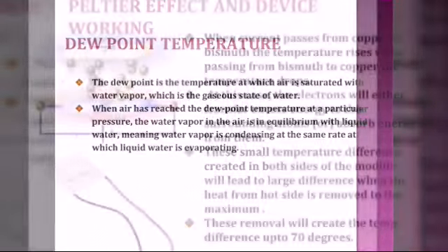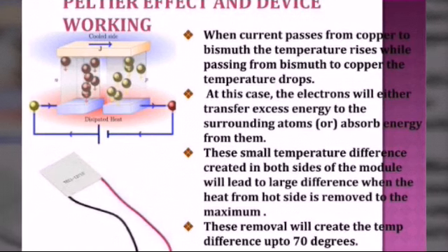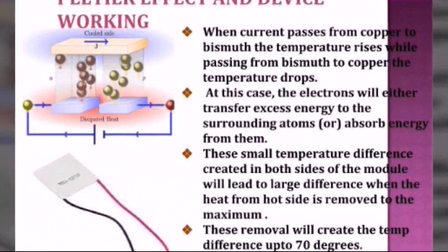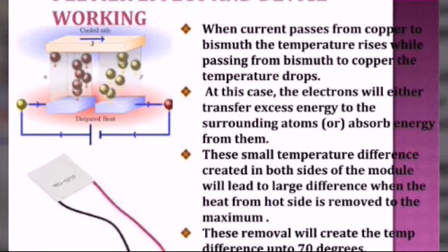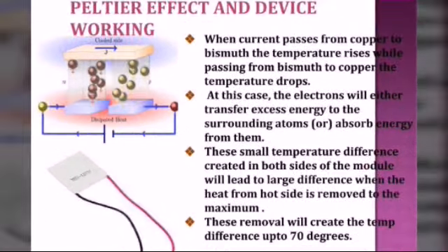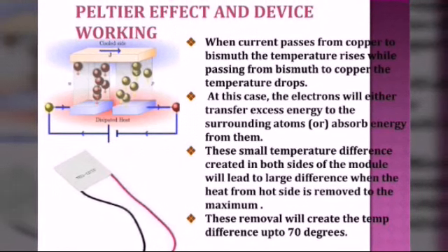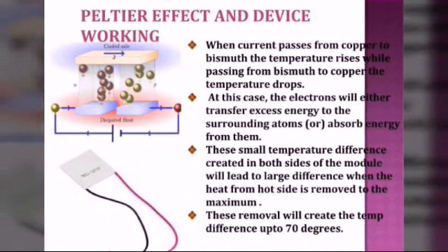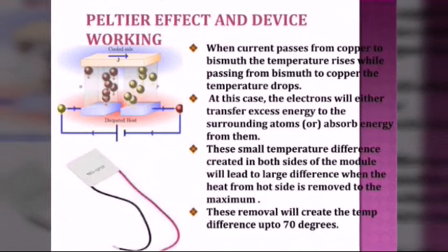For the production of water, the cooling part mainly works based on the Peltier effect. For condensation to occur, cooling is needed. This is artificially produced by using the Peltier element, which works based on the Peltier effect. The Peltier element produces cooling on one surface and heat on the other. It works by joining two different semiconducting materials.